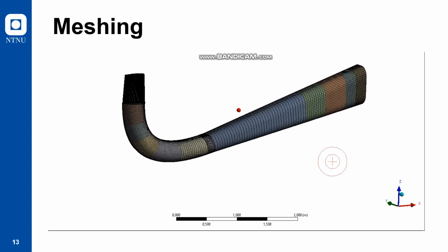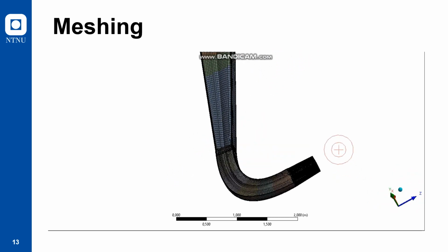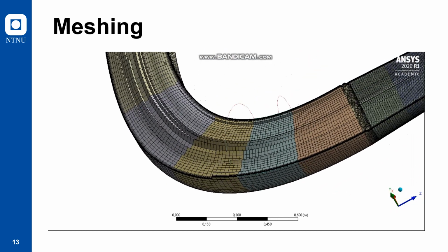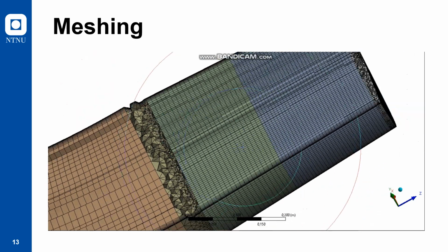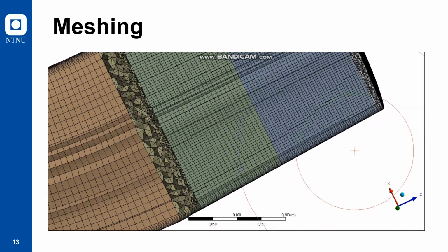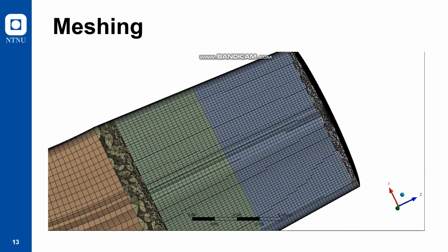Here you can see a mesh I've used for some of my simulations this far. It mostly consists of hexahedral elements, but has some zones of tetrahedrons, as this opens the possibility to change the resolution of elements throughout the draft tube. In the cone, the resolution of cells is much finer to capture the complex flow field, as well as close to the wall, where the mesh is finer to better model the boundary layers.